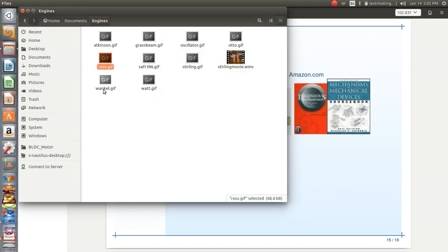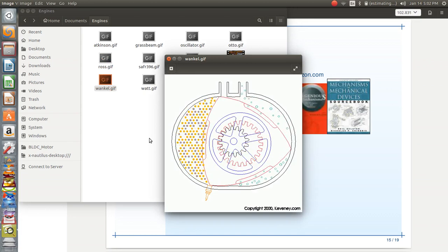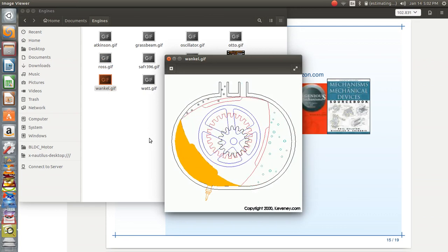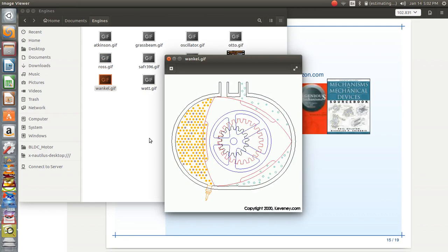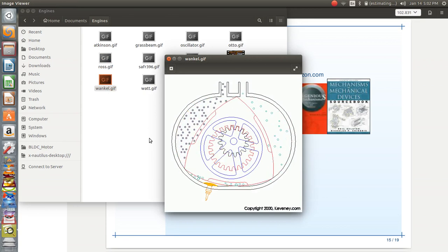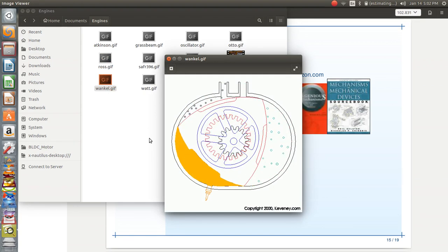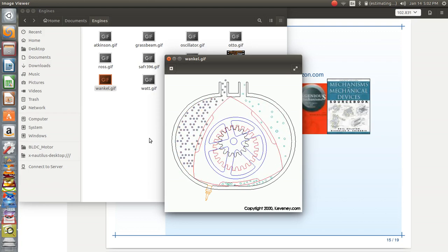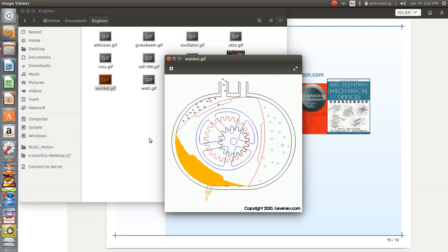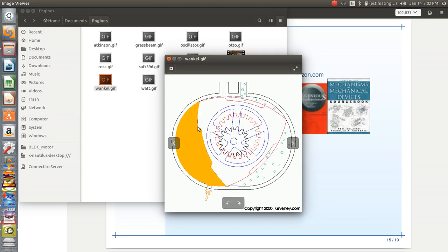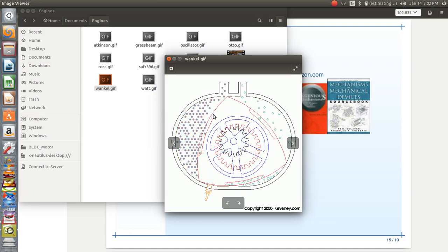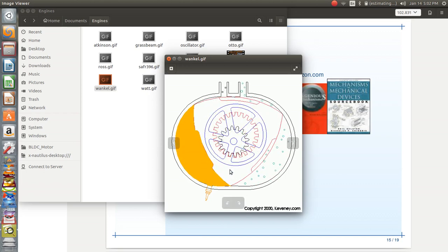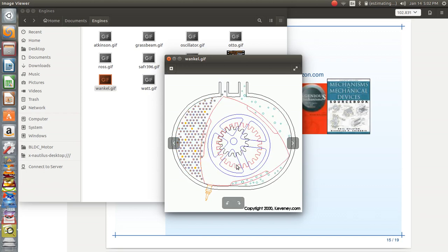Everyone always likes the Wankel rotary engine. This is actually an implementation of the Otto cycle, but with very, very different hardware. This was developed and actually managed to bankrupt a company in Europe, the company that developed it. The only company that has effectively marketed Wankel rotary engines is Mazda. But Wankels have a couple of problems. If you note the tips of this interesting looking triangle, that is where the seals must be effective for a Wankel engine to work properly. And that's a very difficult technical challenge.